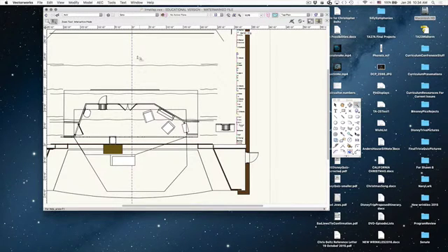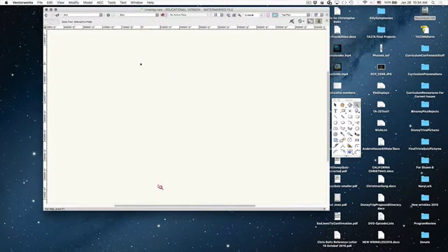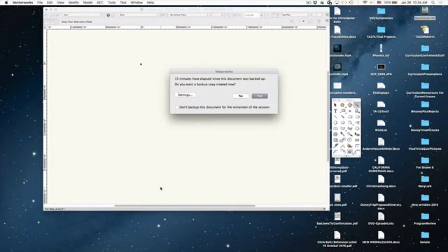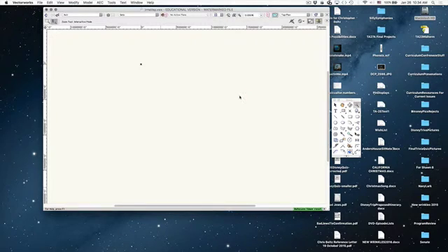The other tool I want to show you in my zoom interactive mode, let's say I accidentally click and I've zoomed out and oh my gosh, I can't find anything because I am zoomed so far out. No, not save. You guys should save regularly. I'm messing around, so I'm not saving. Okay, and let's say you can't find that X has gotten so small you can't figure out that that's our drawing. You want to get back to where we were. This button right here is a fit to objects. If you have nothing selected, it's going to zoom so that all the objects that are visible fill your screen.